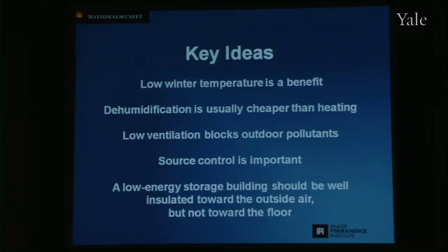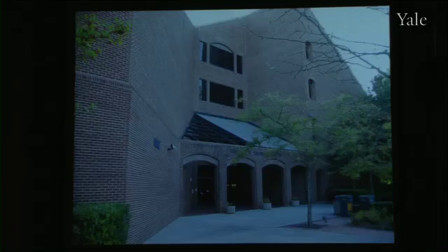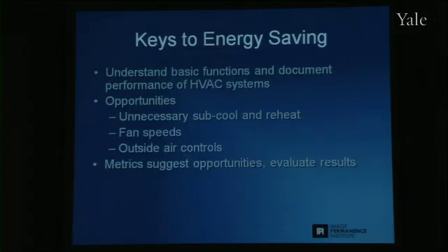The slab, the concrete floor, is doing all the work of heating and cooling it. And they've discovered that it's important that the floor not be insulated, but the walls, the side walls and roof, be insulated very well thermally. So when we come back and look at our own buildings, I think there are lots of lessons and lots of opportunity for sustainability improvements. And the last thing I want to show you is a little list of things to look at to save energy in a building like we have, and like most of our libraries and museums.